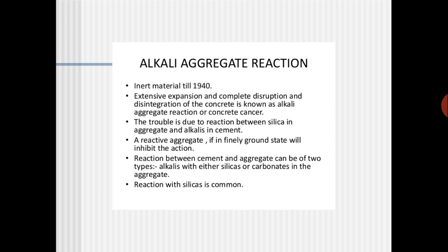So of course it is a common reaction. It has been studied since 1940. Extensive expansion and the complete disruption and disintegration of the concrete is known as alkali aggregate reaction or the concrete cancer. The trouble is due to the reaction between the silica in the aggregate and the alkalis in the cement. We already said that silica is present not only in the aggregate, it is present in cement and in sand also. Silica is the main component.